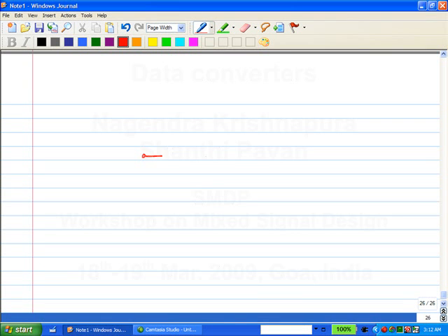What we are trying to do is, if these are VA and VB, generate a current which is GM times VA minus VB. Now, for those of you who have exposure to transistor level design, can you think of a simple circuit which will take the difference between two voltages and convert it into a current?